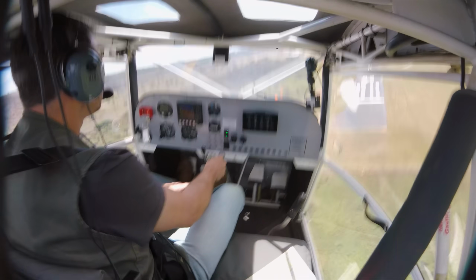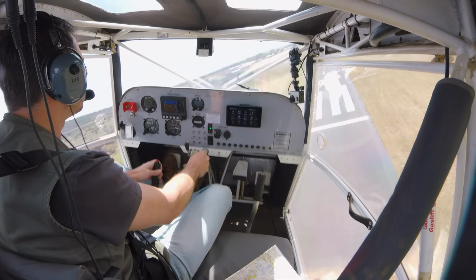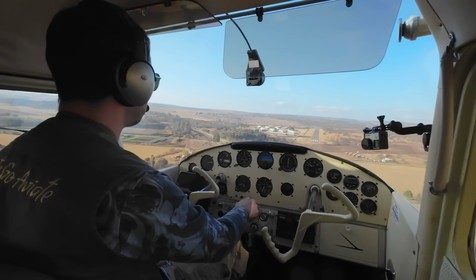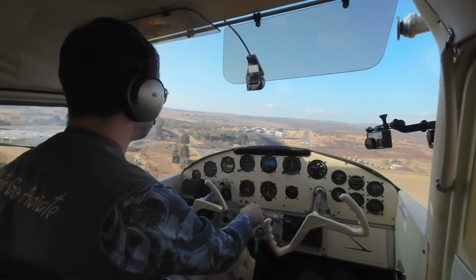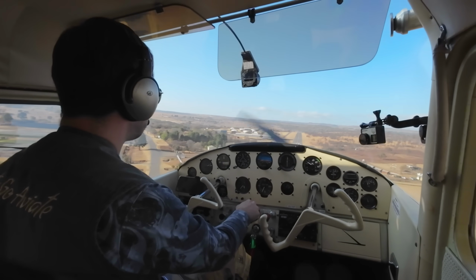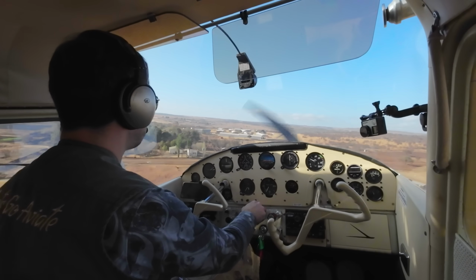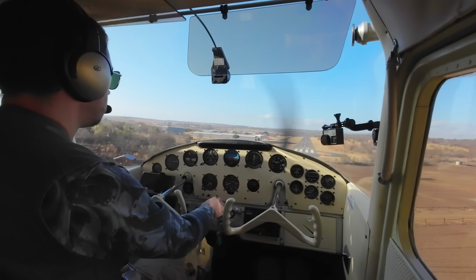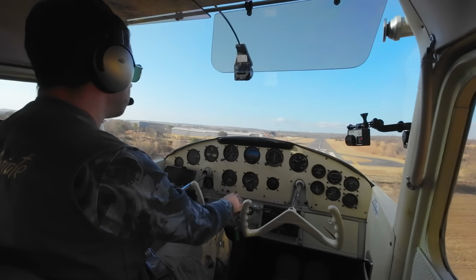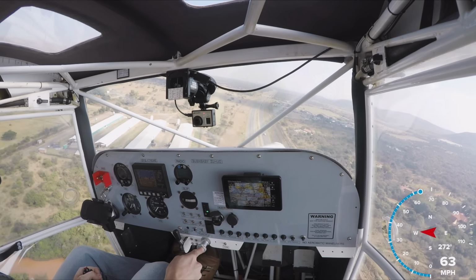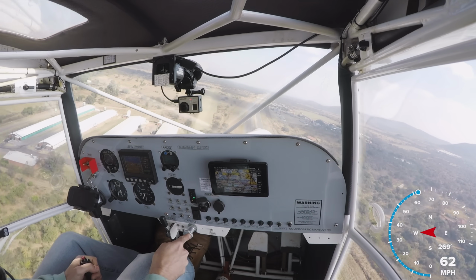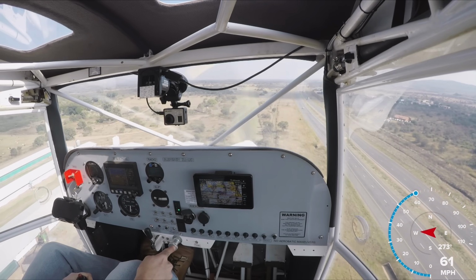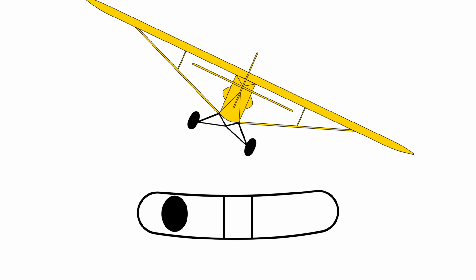Why is that? Because you're not pulling the yoke back anywhere near fully aft. In fact, you're likely pushing slightly forward to keep airspeed on target due to the increased drag. That's what increases your descent rate and is why you are slipping in the first place, to descend faster without increasing airspeed. Due to that forward input on the yoke, the wings remain well below critical angle of attack, even though it's uncoordinated flight. What about a skidding turn?